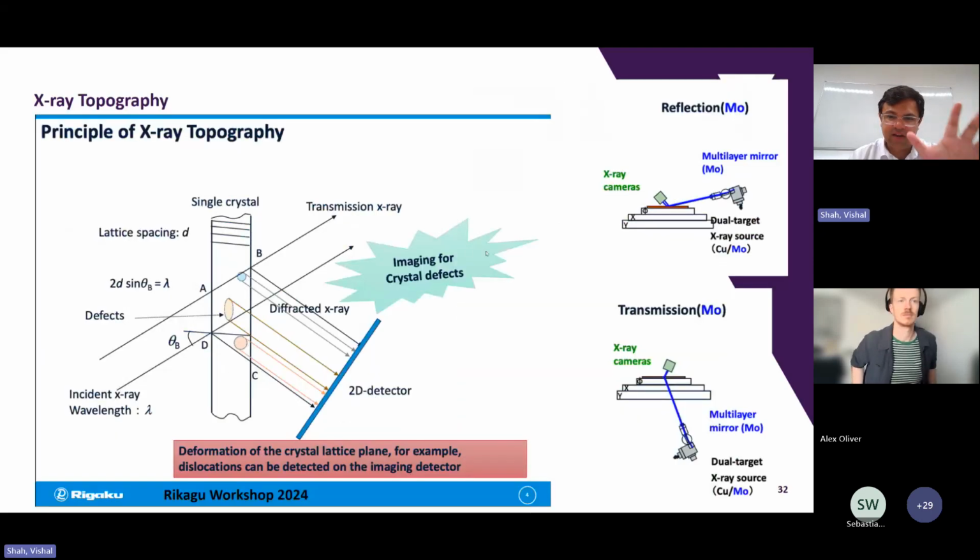Another standard which has just come in is X-ray topography, and that has come in both in the SEMI standards and in the JEDEC standards, and that's been translated to the IEC standards as well. And this is quite a nice technique where you shine X-rays onto a crystal plane. It acts like a disco ball, so you can look at lots of different images and they might tell you something about a different type of defect.